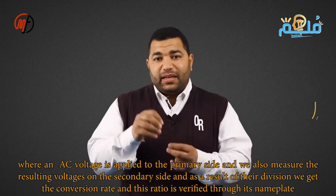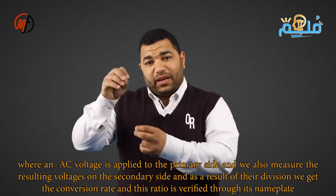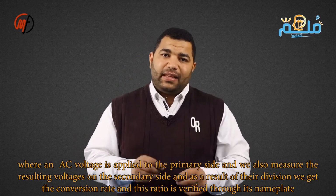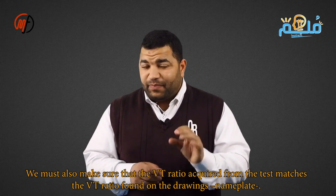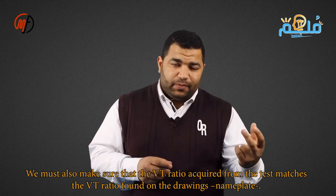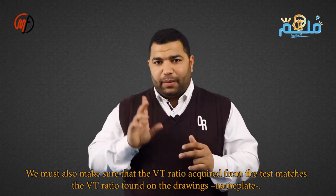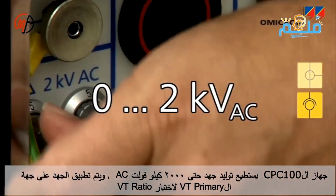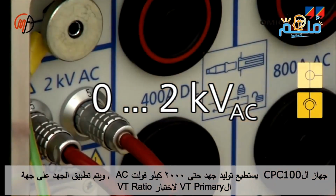Ensure the actual VT ratio matches the VT ratio on the nameplate. The PC100 can generate up to 2000 volts AC for injecting into the VT's primary side to verify its ratio.